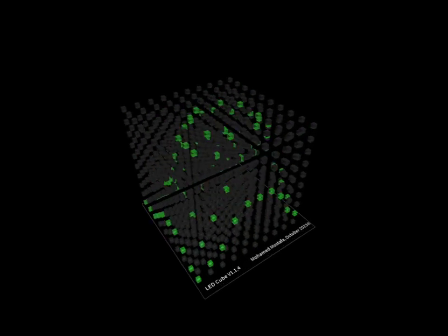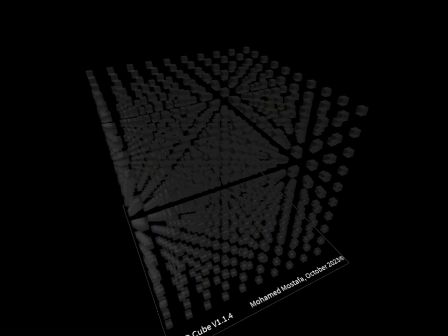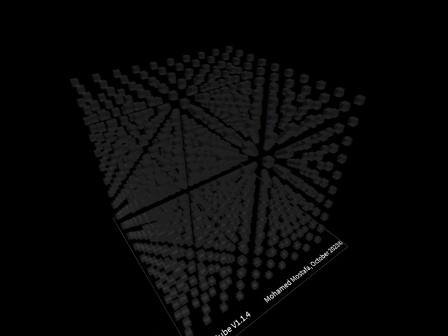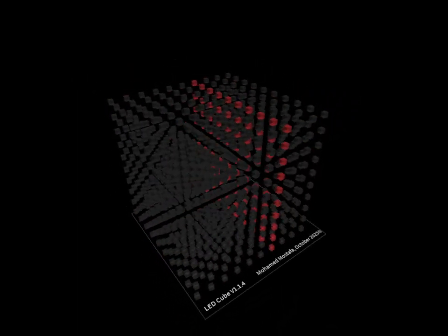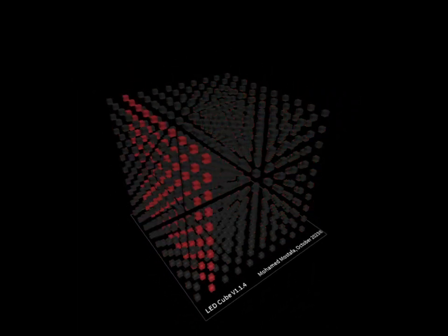512x LEDs, plus some extra for making mistakes. 64x resistors. See separate step for ohm value. 1x or 2x large prototype PCBs. The type with copper eyes, see image. 1x ATmega32 microcontroller, you can also use the pin-compatible ATmega16. 3x status LEDs. You choose color and size. 3x resistors for the status LEDs.